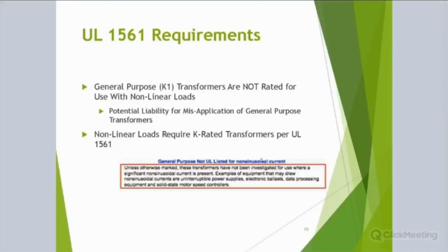So they make a point that nonlinear loads require K-rated transformers, but yet they don't tell you what the K rating should be for the different loads. That's really where the engineer comes into play, making sure he's protecting you from the loads you have in your project or in your facility for that design. And I would lean on them to help you with that and make sure that it's covered. And most engineers will protect you in that respect.